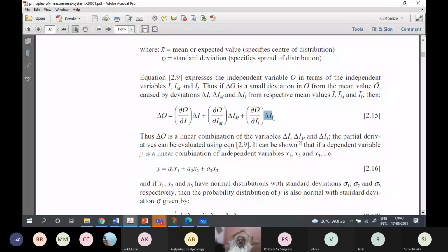When you are measuring the strain of a strain gauge, you don't measure the ambient temperature. Why? Because the output due to the strain is supposed to be much larger, so you sort of ignore it. You are weighing a truck. Since you are weighing a truck, the major input is strain, which is actually coming from the weight. So whether you are making the measurement in summer or winter, that correction you may not do. You may choose to ignore it.